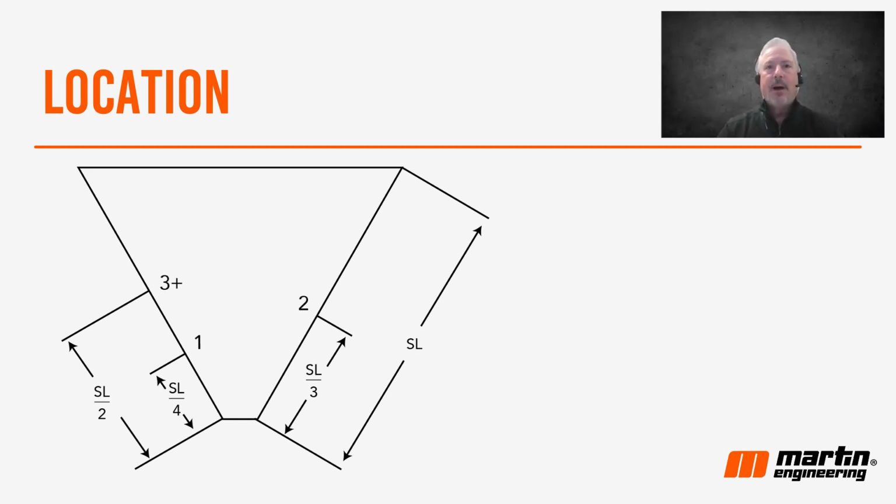In some cases, we might have to recommend 2 or 3 or more. It's rare, but sometimes. And one of the scenarios would be a thinner wall than what the force output requirement would be. We'll split that force up and use 2 vibrators. As you'll see, number 2 there is on the opposite wall, a third of the way up the slope. And in those rare instances, we'll go halfway up the slope with other vibrators mounted on the other available sides of the structure. So location matters on this so that we can effectively move the material.